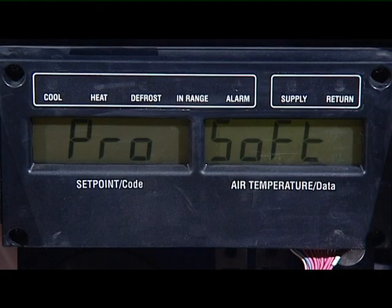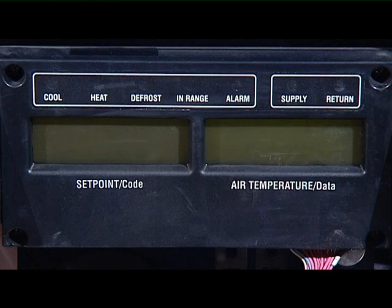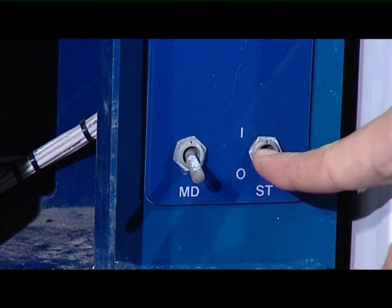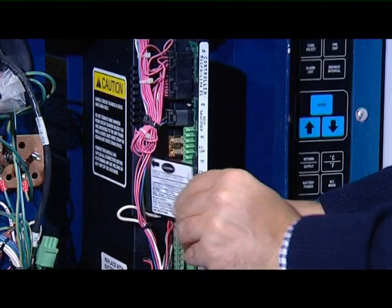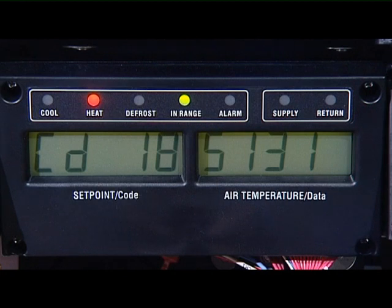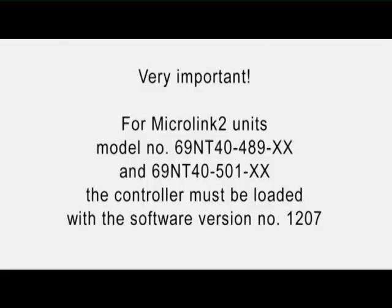The display will show the message Pro Soft. This message will flash till programming is finished. Wait until the display shows the message Pro Done. Switch off the unit. Remove the card. Switch the unit back on and verify the software version has been loaded by selecting code 18.